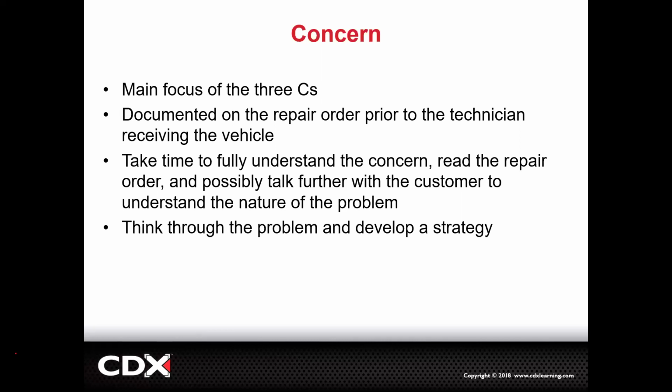So when I talk with the customer and they say, oh, my AC blows warm, I'm going to say, all right, well, does it always blow warm or did it happen recently? Was it blowing cold and then all of a sudden, boom, it blew warm? Or did you feel like it was blowing cold, then cool, then kind of cool, then kind of warm, and now it's blowing full warm? Anybody think they know why I would ask it like that? Do you see what I'm driving at if I ask it like that?